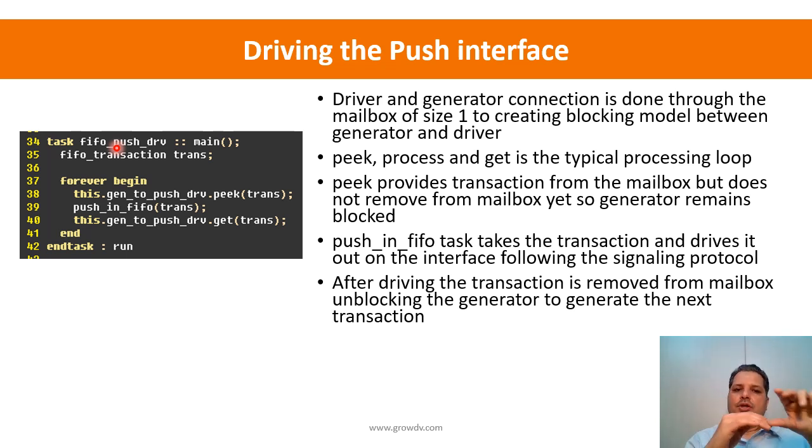The bottom part connects to the DUT using the virtual interface, and the top part connects to the generator using the mailbox that we had declared, named gen to push driver. The mailbox is a construct provided in SystemVerilog, meant for interprocess communication.